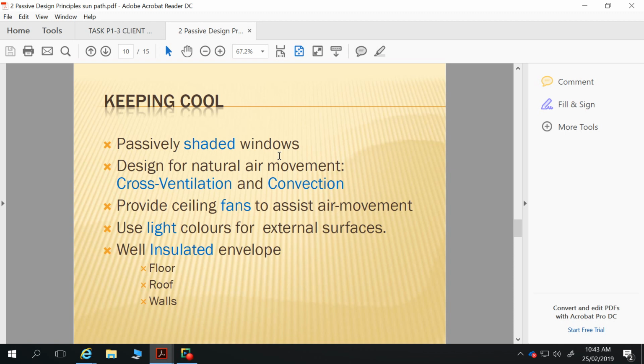So our eyes see these dark colours and go, yeah, there's not much light coming off of that, but light is also a source of heat. So as we get that solar radiation coming down, dark colours are reflecting less of that and absorbing more of it, whereas light colours like white and silver and highly reflective surfaces are reflecting that light, that solar radiation that's hitting them. So lighter colour roofs are better.